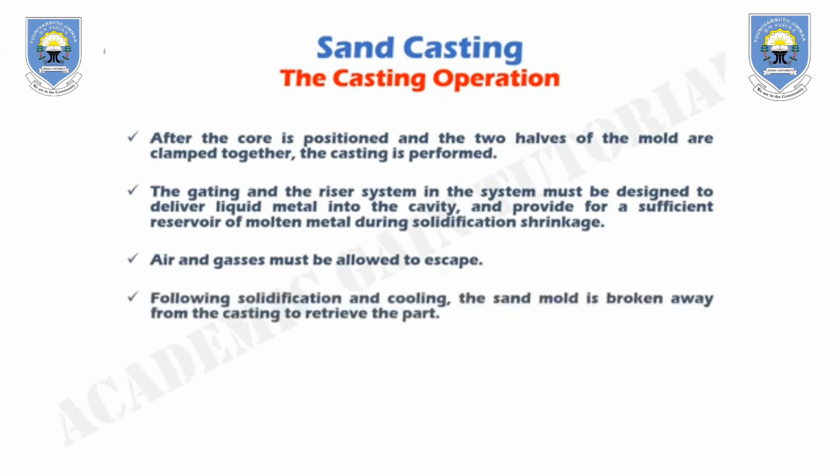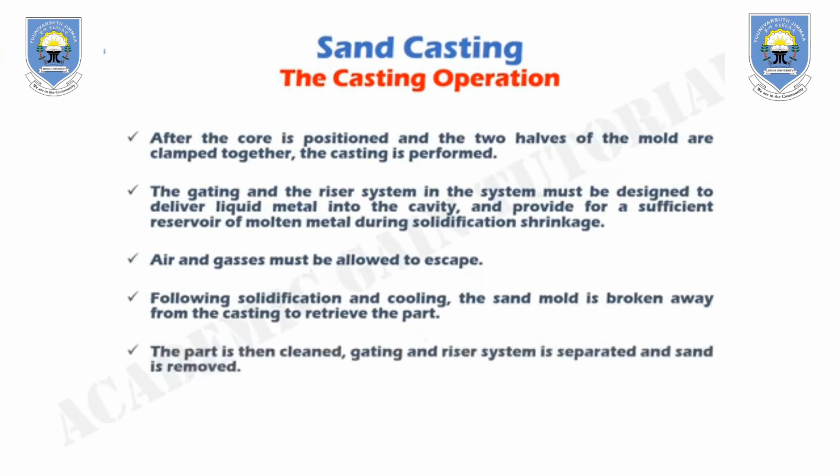Following solidification and cooling, the sand mold is broken away from the casting to retrieve the part. The part is then cleaned, the gating and riser system is separated, and sand is removed. Finally, the casting is inspected, completing the casting operation.